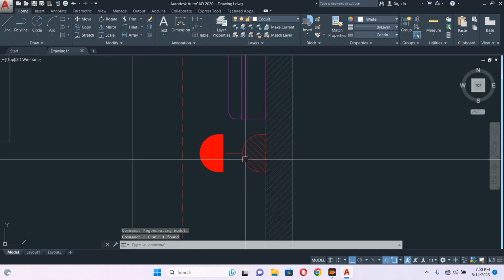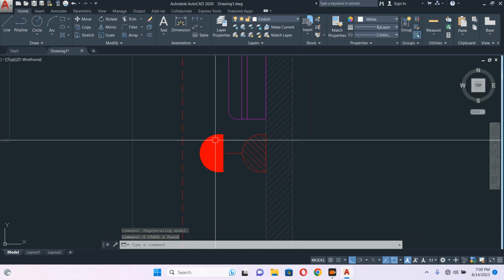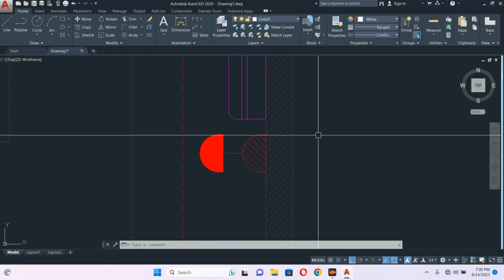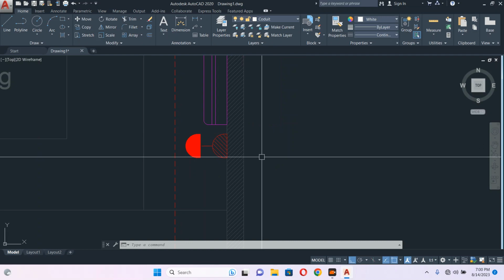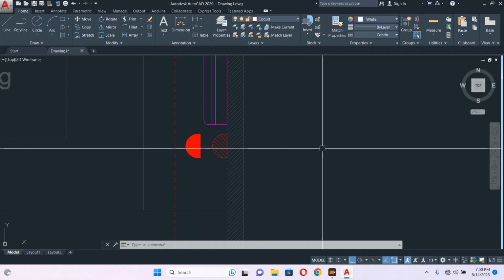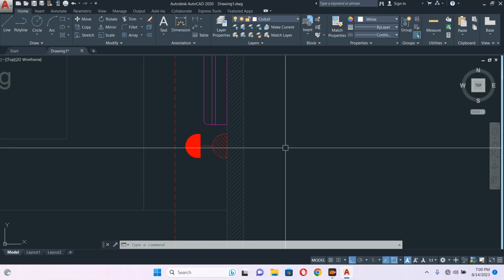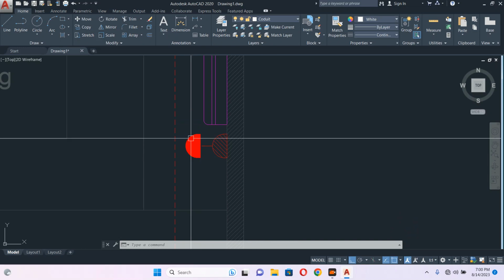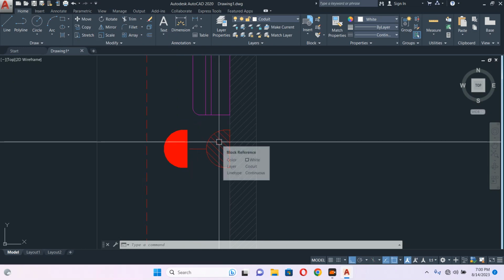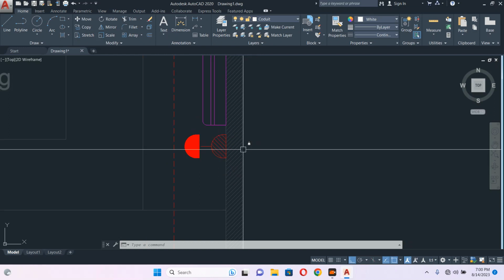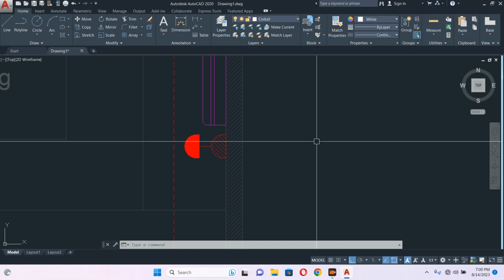So this one 20 ampere, this one 20 ampere, the isolator 20 ampere, and the breaker also 20 ampere. All should be 20 ampere. This one can be 40 ampere, no problem, and this one can also be more, no problem. The isolator you can also put at 40 ampere, no problem. But the breaker should not go more than 20 ampere.